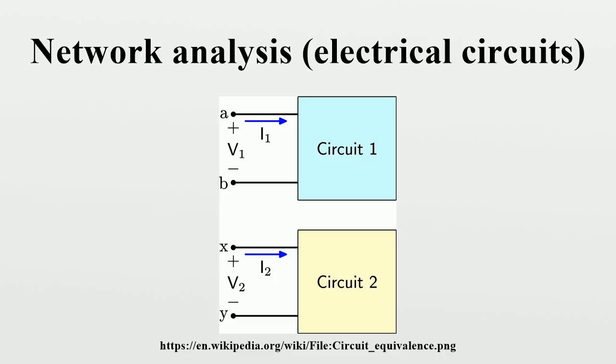Mesh analysis. Mesh: a loop that does not contain an inner loop. 1. Count the number of window panes in the circuit. Assign a mesh current to each window pane. 2. Write a KVL equation for every mesh whose current is unknown. 3. Solve the resulting equations.